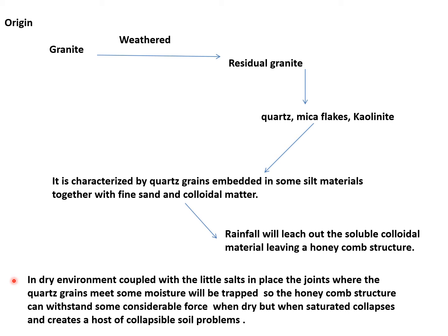In dry environment, coupled with the little salts in place, the joints where the quartz grains meet, some moisture will be trapped, so the honeycomb structure can withstand some considerable force when dry, but when saturated, collapses and creates a host of collapsible soil problems.